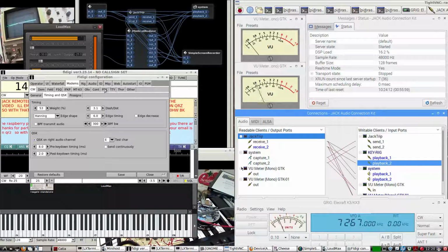The reason we do that is the K3 operates CW much better if the push to talk jack is down first. So I'm able to time it by hitting the push to talk 8 milliseconds before the CW jack is keyed. And after the CW jack is finished, it hangs on just an extra 2 milliseconds so that there's no clipping of the RF wave, there's no shortening of dits, and there's some dit variancy on the K3, and that is cut in half.